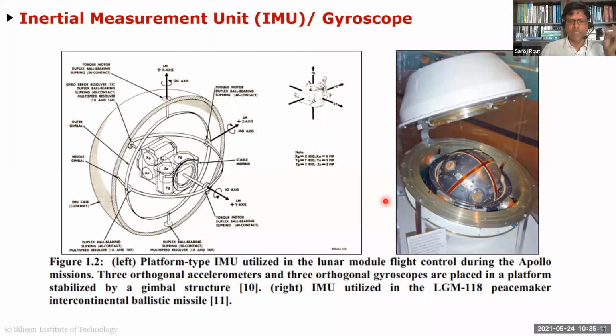The reason is from that point onwards, they use what's called the inertial measurement unit, which is primarily a gyroscope, accelerometer, and a magnetometer, three things put together. Just based on your rotation and your speed, it knows locally. But because of noise, you can't do that for long, and that's the challenge in building this. I've been consulting for a company for the last 8 years or so to design one of these IMU units, and they still don't have a sample. They take a long time to get the noise really, really low.